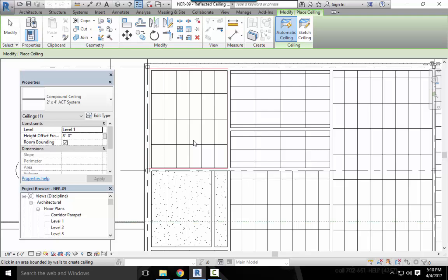I've seen that happen on drawings before where somebody has offset something and not realized it, and they end up with a 3 foot piece of tile in the middle of the floor of the room. Hopefully that gets caught during construction and you make the necessary adjustments, but it's very difficult to make that mistake here. Alright. Item 7, with the ceiling command still running, select the compound gypsum wall board on metal stud.